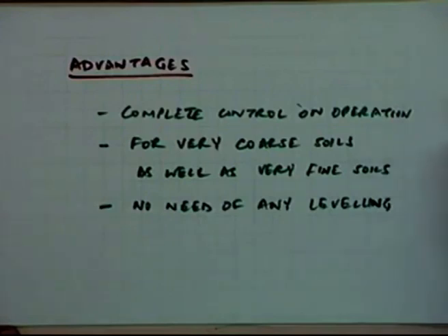You can use this method because in this case you don't have any problem of the terrain, as the rate of application is in your hand. You can wait for the soil to be dry so that next time when you apply the irrigation water, there is no surface runoff. In the beginning, the infiltration rates will be high.